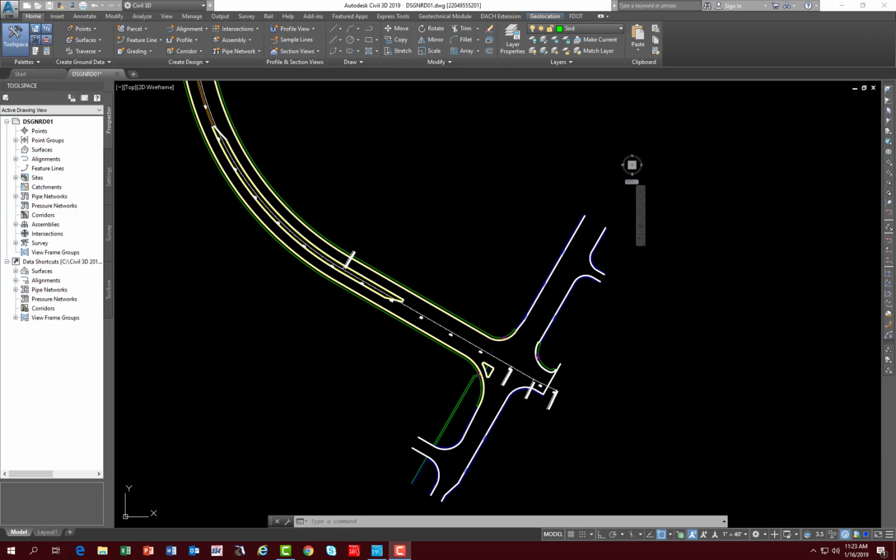The advantage of Civil 3D is some of the line work will come from the corridor model in the form of feature lines, which are either 2D or 3D. The roadway designer should keep this in mind when the model is complete, that the line work should be extracted for use with quantities.